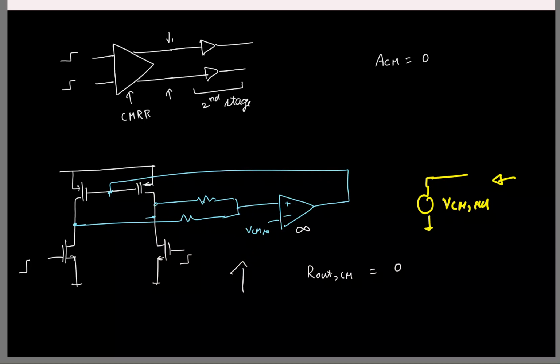And remember, all this is possible because this amplifier is tweaking this gate voltage here to keep my output common mode to be fixed. Okay. With infinite gain the output resistance is 0. With finite gain it will be a small number. Okay. But there is one catch. So here let us say again, as usual, I apply a common mode step here.